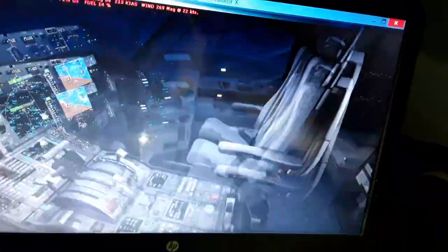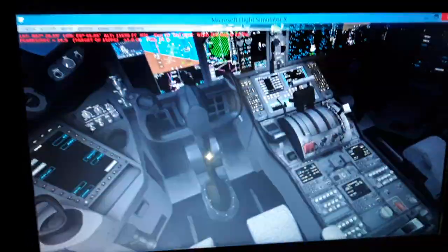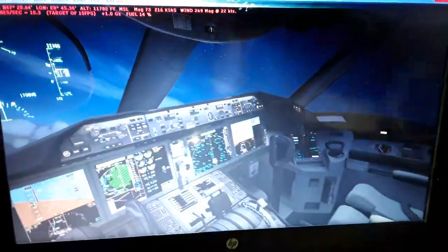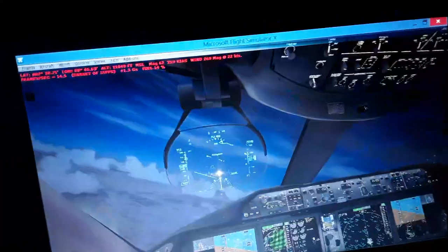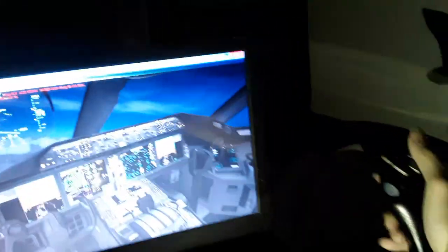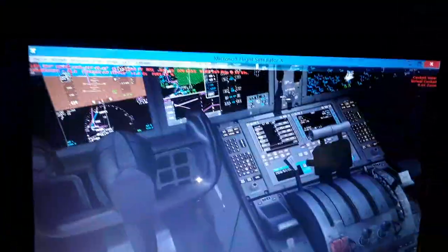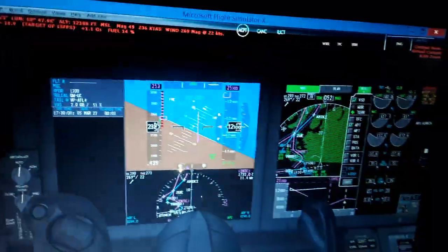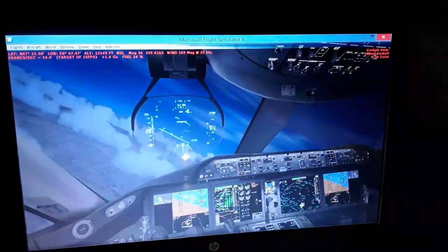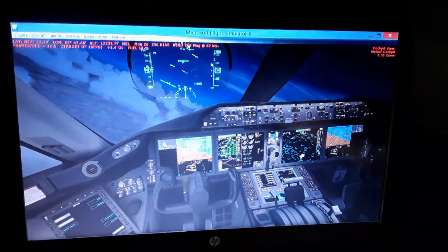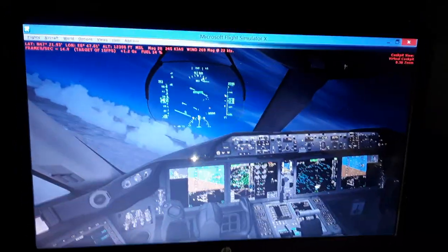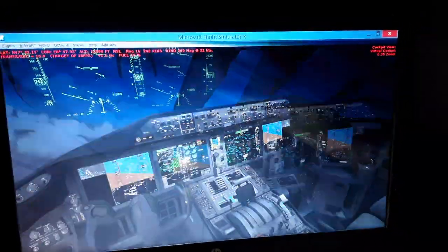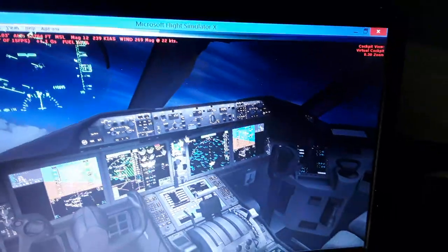So this is the view of the cockpit as we're climbing the Boeing 787. You can see we can leave the hands off from the side stick, no problem. We have no autopilot yet connected. So we need to follow this purple line as we turn, usually a bit left rudder to make it faster and more coordinated turn.